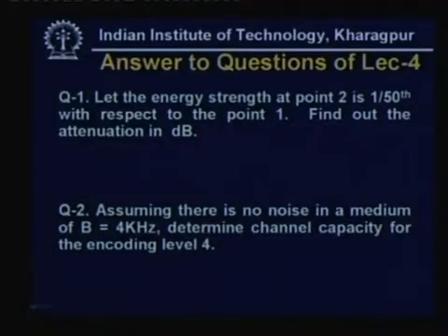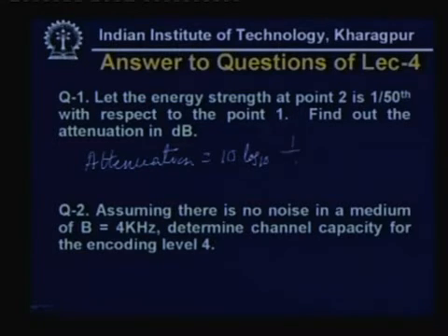So here are the questions that I gave in the previous lecture. Let us look at the first question. Answer is attenuation. Attenuation will be equal to 10 log 10 1 by 50. So this will be equal to minus 16.9 dB.